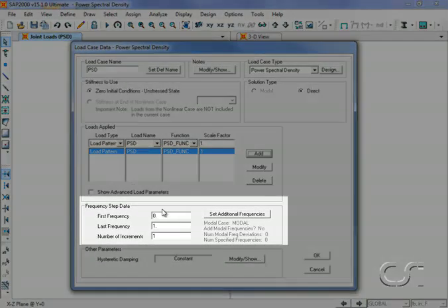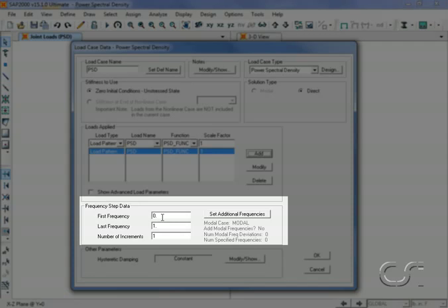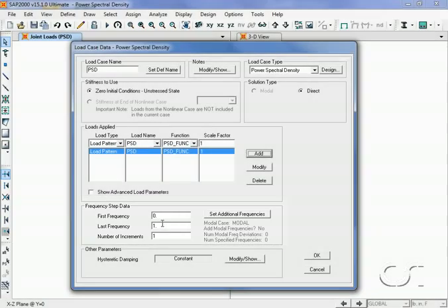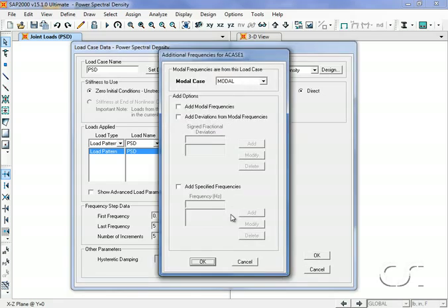One of the most critical steps in the data definition process is setting the frequencies. This controls the shape of the output spectral density curves and thus ultimately the RMS values. We will start with a basic selection of whole number values of 0 through 5, but we'll need to add significantly more points, especially around the frequency of the model. We will use the Set Modal Frequencies option.